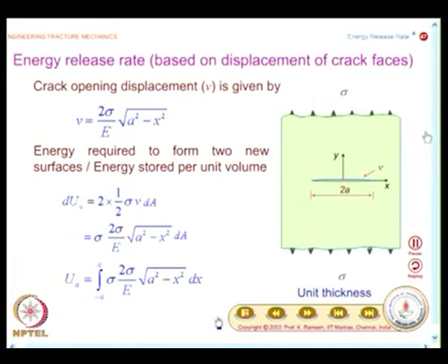You can actually put the horizontal stress component here, the result is valid, and the ultimate interrelationship between G and K still remains the same. In the initial stages of development, people focused only on the crack and were used to looking at uniaxial loading. Because of force of habit, they used it, and that is the way we have to take it.